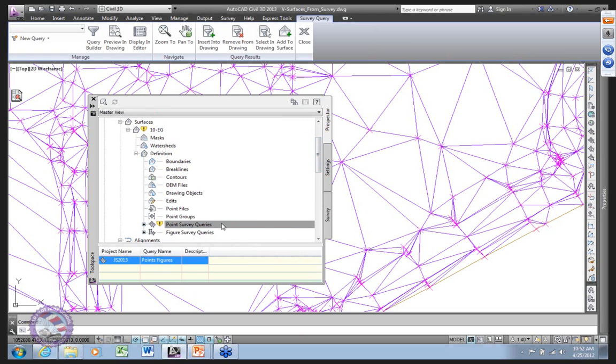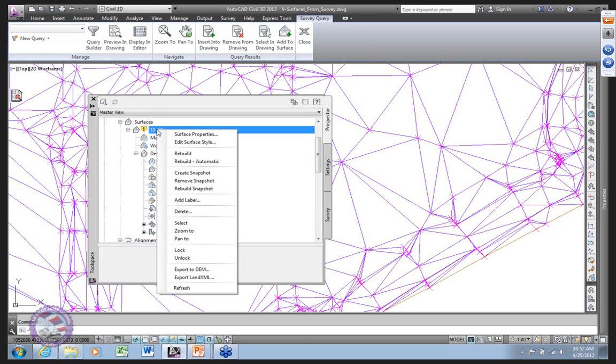Okay, so I can rename, but you got to tell the surface, hey, things have changed. And then it goes, hey, things have changed. Okay, remember, everything in Civil 3D is connected by this idea of names. And if you've got one figure and you rename things, you better make sure you pay attention.